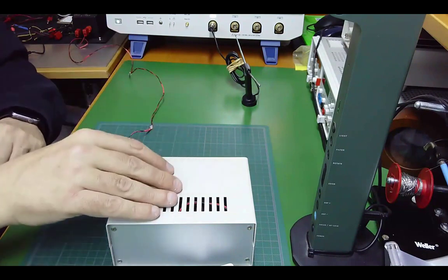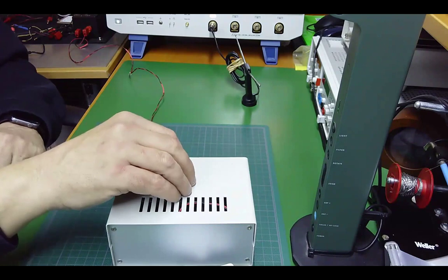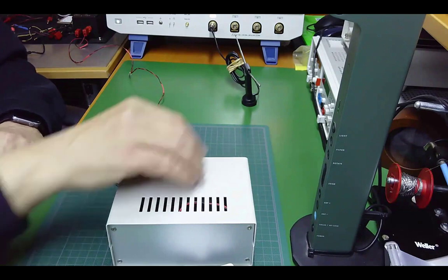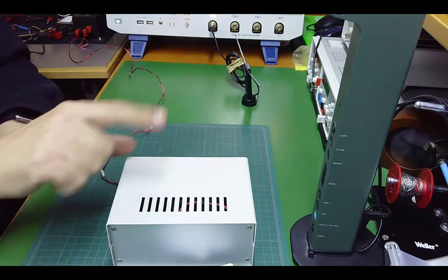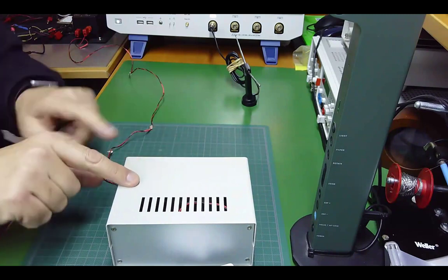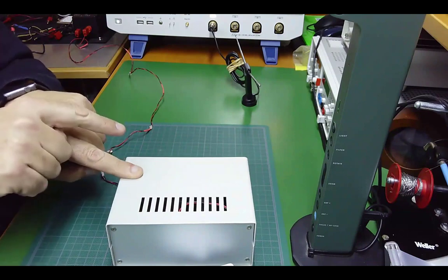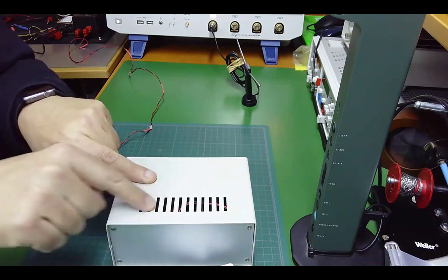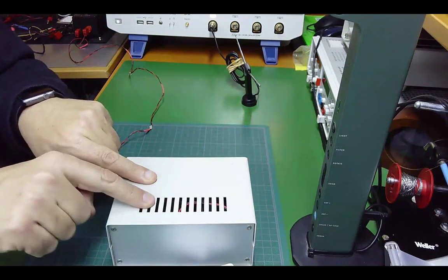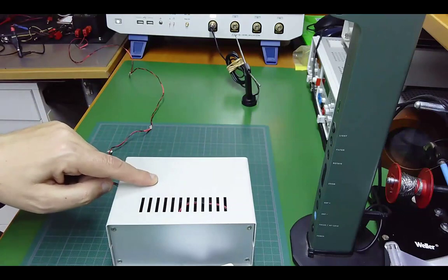What I am going to consider is that the electronics inside is shielded. So the electronics inside is not being coupled to the antenna easily, but perhaps the energy is going out through the slots or the apertures. But then you need to compare the frequencies where you are experiencing the problem with the size of the slots. In my case, if we consider that we are around 100, 200 megahertz, the wavelength for 100, 200 megahertz is perhaps something like 3 meters.